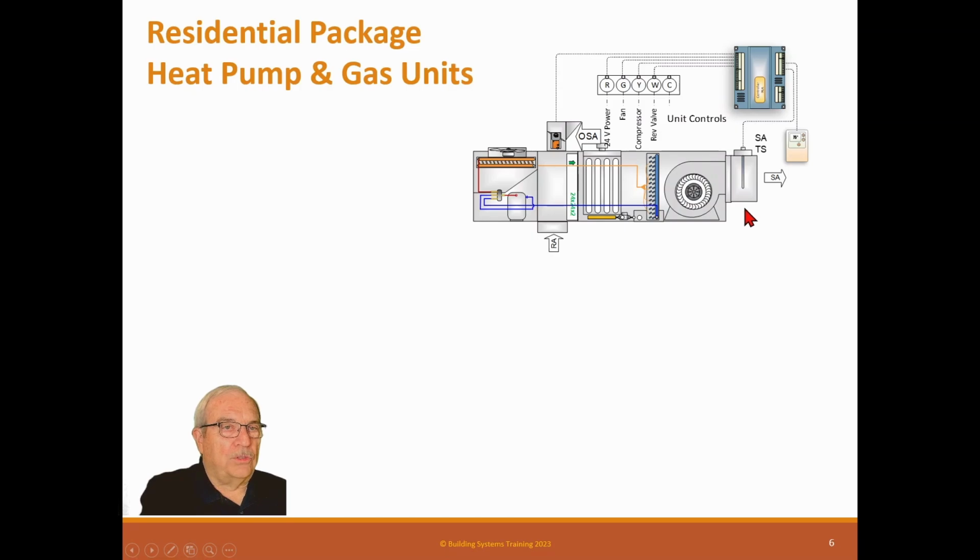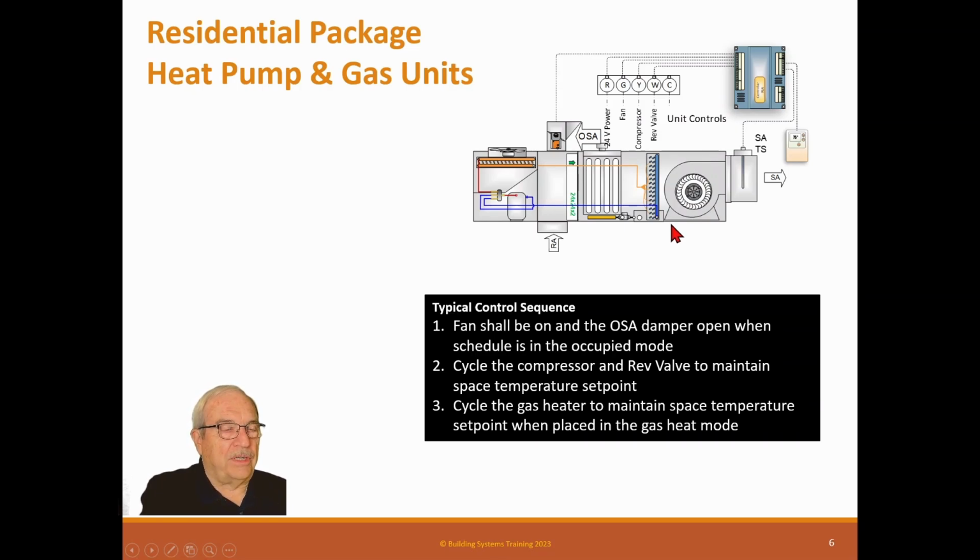So if you're in a cooling mode and you get a complaint that it's too warm, and you look at the unit graphic and it says we got 80 degrees or 75 degrees leaving the unit, something's not working. Now, you don't know what it is, but it could be a bad compressor, a clogged filter, it's out of gas, it's had a leak, or this fan is off. Either way, it'll tell you. So it's the most economical status point we've got.